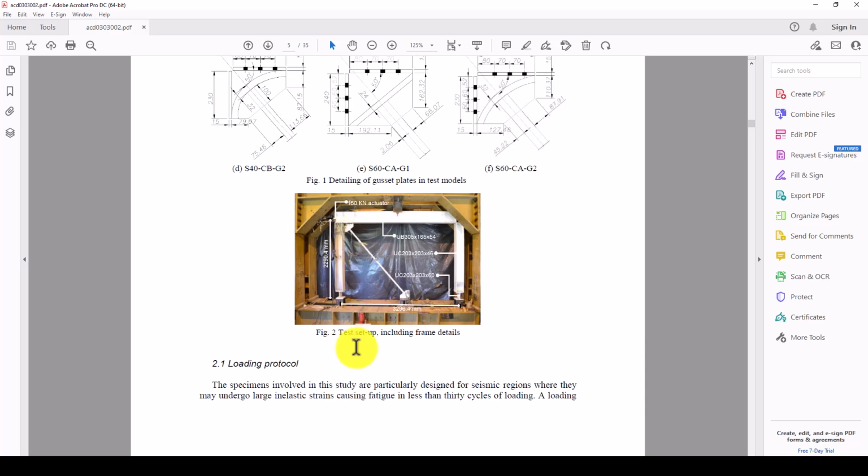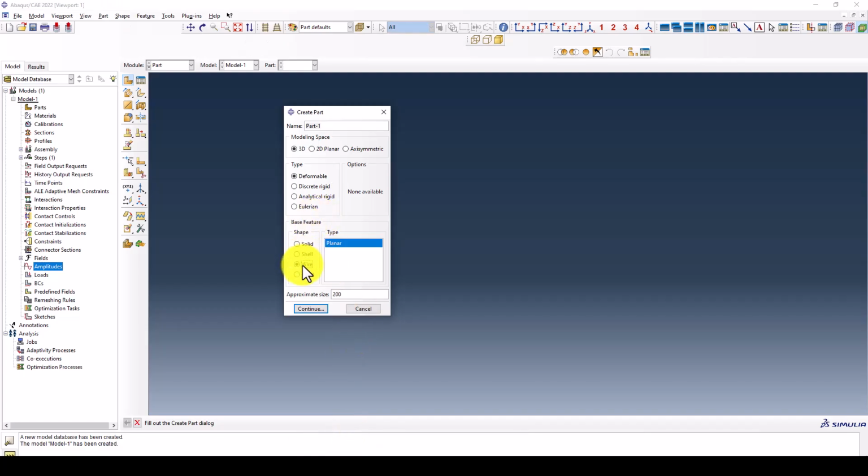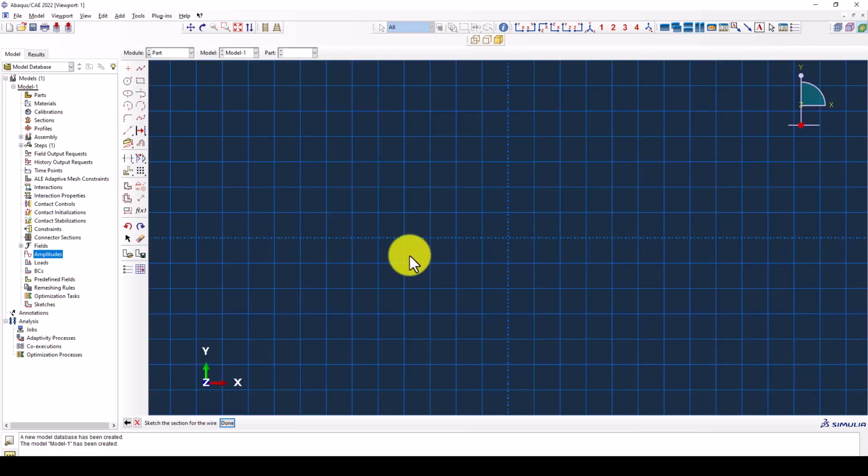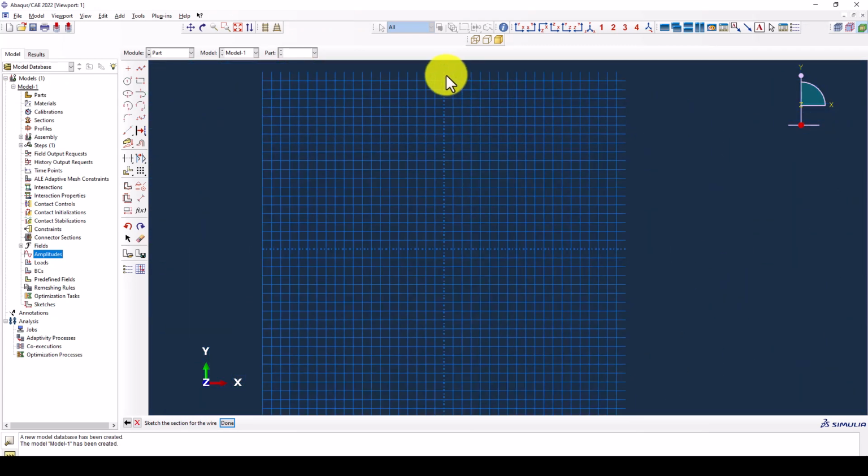So I use wire and just a frame, and the program automatically considers it rigid. The units I'm going to use are millimeter, Newton, and ton. Now I want to extend the sheet size to, let's suppose, 8,000 millimeters, and when I draw 4 meters by 3, it will be exactly this area.